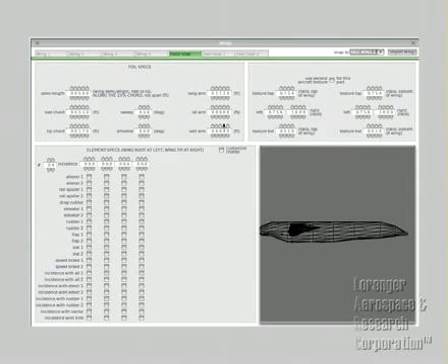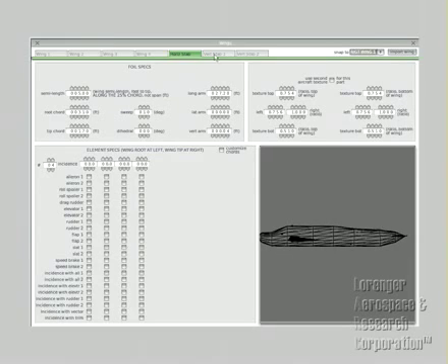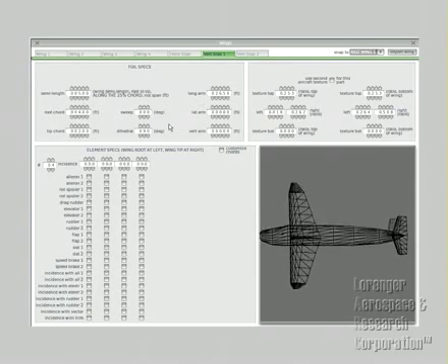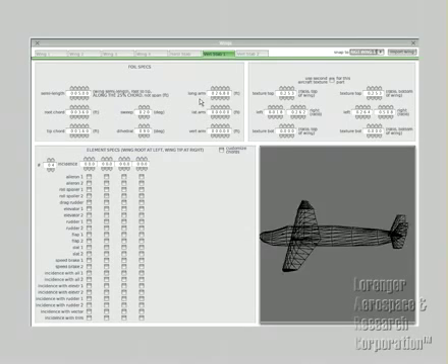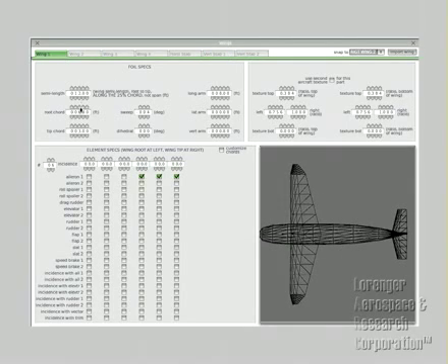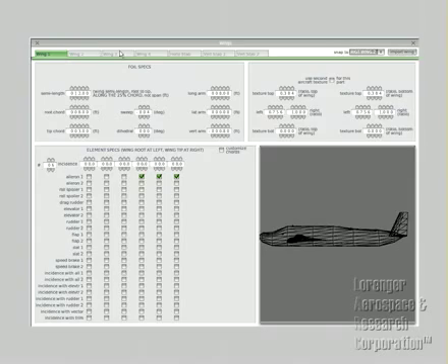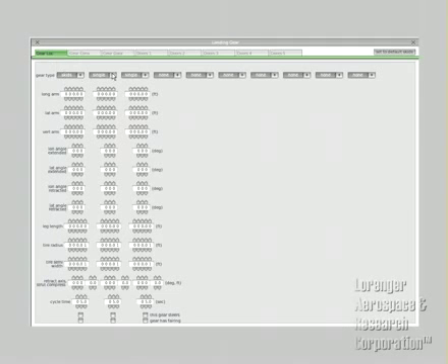What you're going to need to do here is design your plane based off of performance. Right now, if you look, it's a very long aircraft, 27, 28 feet long, and it has a long moment arm. You see where the control surfaces are? Since it has such a long moment arm, you do not need large surfaces because it will actually cause instability issues, and you can overstress the airframe. More on that later. Again, you should know exactly what you're designing before you attempt to do this. I didn't, so you're seeing all the errors as we do it. But you will run into these errors, so bear with us.